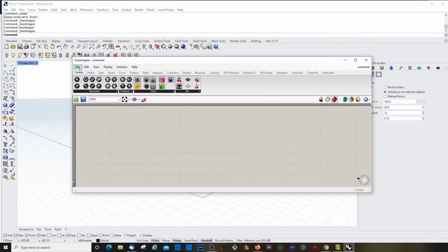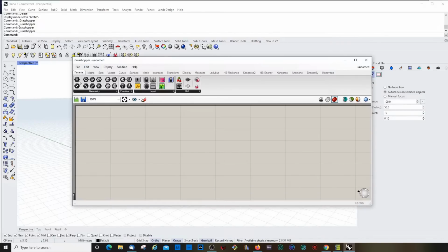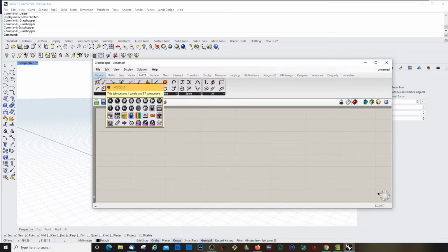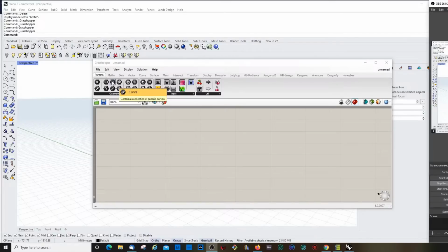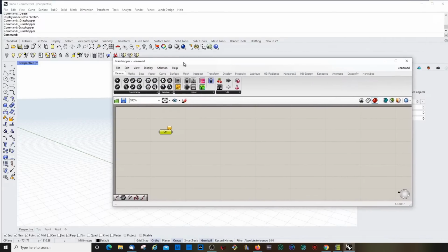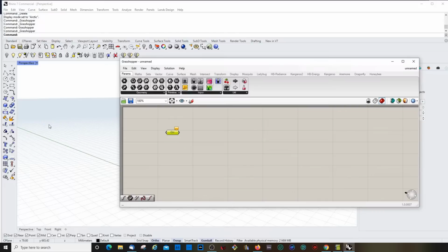Normally, if you open it, it would be like this. So it would be here on the parameters section. We went briefly through how to construct a point and how to deconstruct a point. And now we go into the next one, which is curves. Also in the parameters, there are these geometry containers, as they are called. For example, here we have point container, circle container, and we have a curve container. There are different containers, and what it means, they can make curves which are, for example, inside 3D world in Rhino, can be made available within Grasshopper.